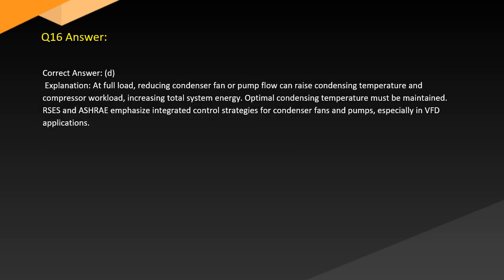Answer. Correct answer, D. Explanation. At full load, reducing condenser fan or pump flow can raise condensing temperature and compressor workload, increasing total system energy. Optimal condensing temperature must be maintained. RSES and ASHRAE emphasize integrated control strategies for condenser fans and pumps, especially in VFD applications.